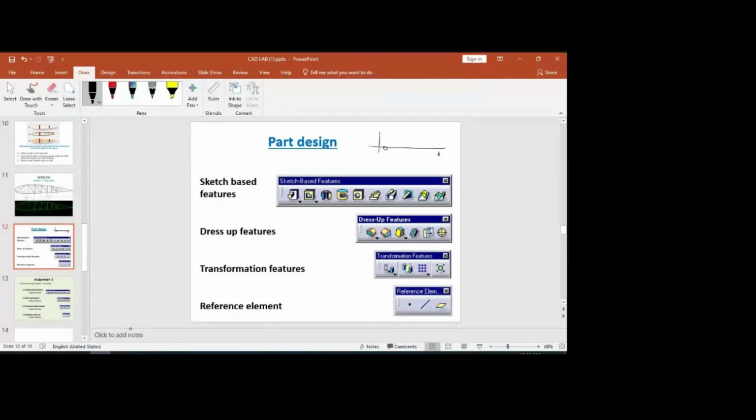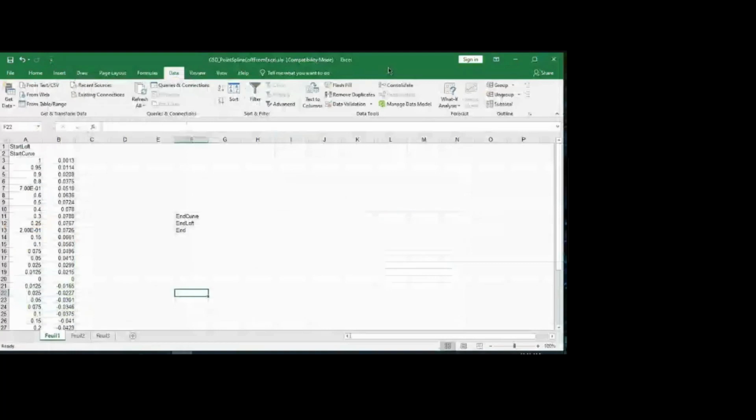It is telling 1 is somewhere 0.0013. Okay, the profile will start like this, will come like this, it won't close. This 1 comma 0 means it will touch this line, then it will be closed. So now it is the open profile. I'm going to make it a closed profile. So instead of this 0.0013, I'm taking 0. Then only we will get the closed profile, because we know with an open profile we cannot proceed further to 3D and so on. Is this step clear?